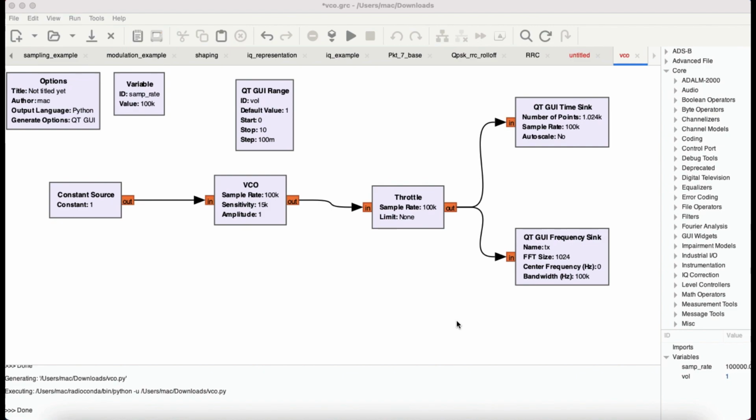In this tutorial, we're going to look at a component which is called VCO, Voltage Control Oscillator. Voltage Control Oscillator is readily available here in your Finder block right here. You can also search for Voltage Control Oscillator, and we're going to look at this oscillator to generate an FM signal. Because what I'm trying to do using GnuRadio Companion is to find out what are some of the blocks that are there, and how can I use them to achieve whatever task that I have.